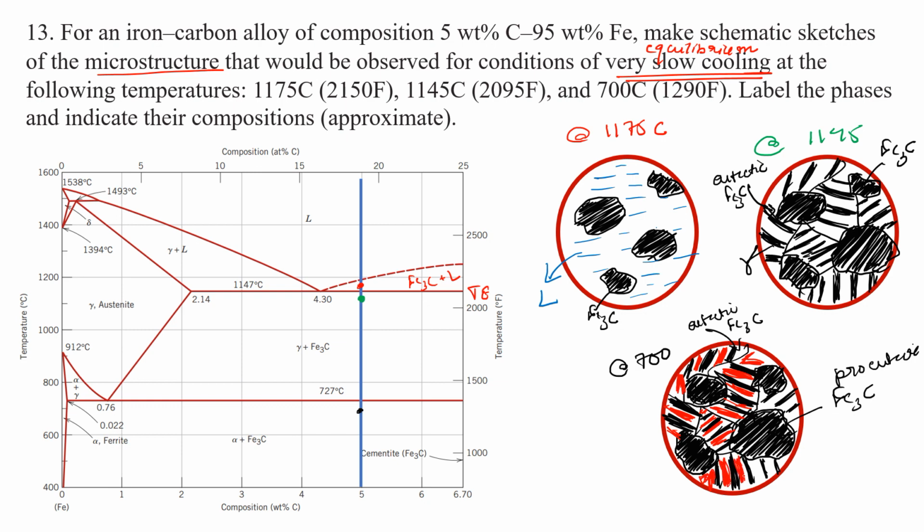If we cool down iron from high temperatures, we see this. You see, we have the delta. It's not delta, sorry, gamma to alpha conversion at 912 degrees centigrade. But in these eutectic cases, we see the transformation happening much lower, at 727 degrees centigrade. So all of these are the eutectoid alpha ferrite basically.